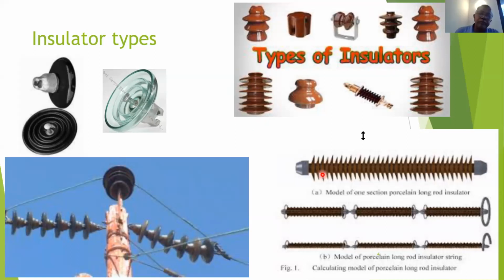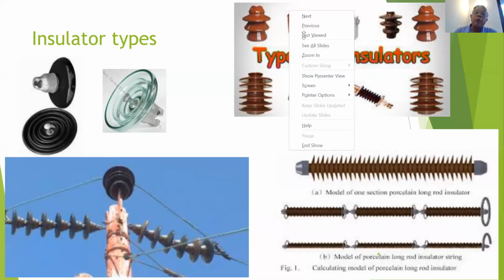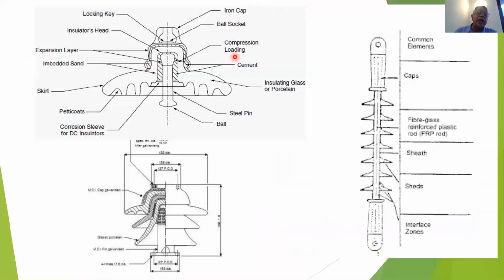Yeah, and this is a long rod insulator. On the bottom also, here it's a long rod insulator, porcelain, and a combination of porcelain long rod insulators. And these are very commonly available as polymer insulators, long rod polymer insulators, not only porcelain insulators. The long rod polymer insulators are more popular and used. Okay, now we'll see quickly a disc insulator.